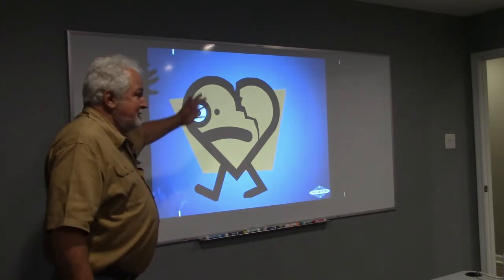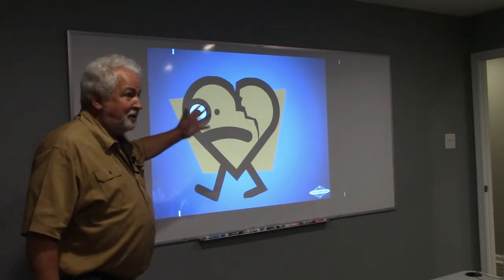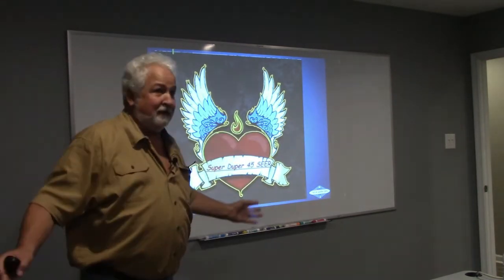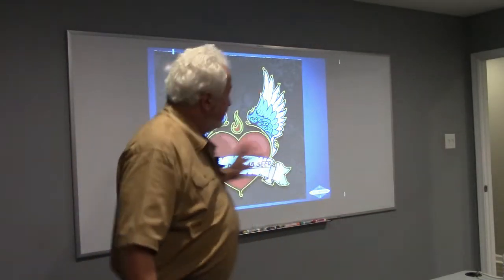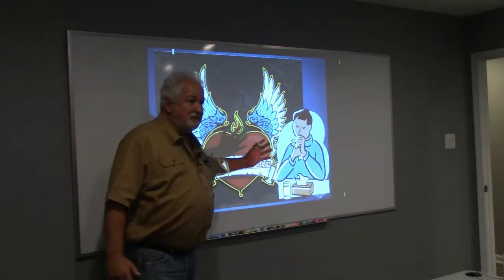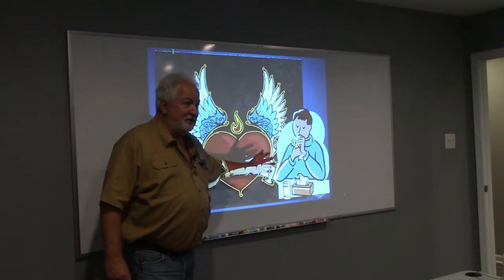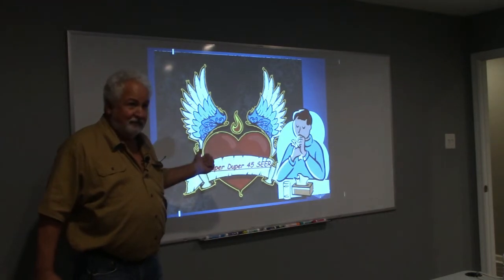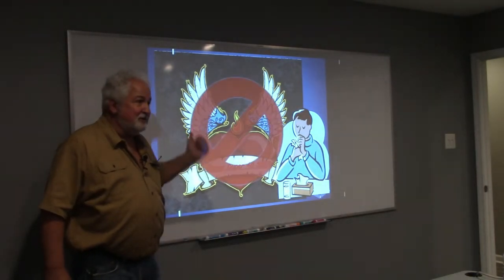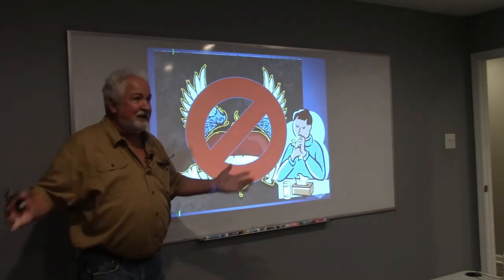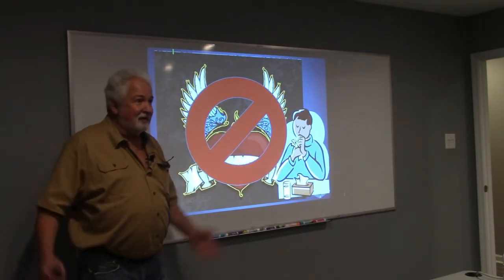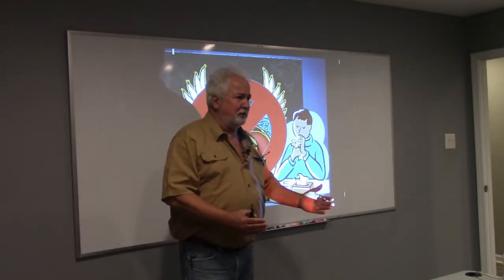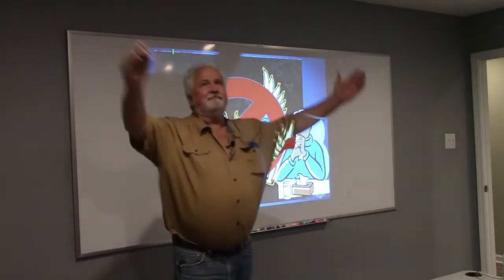So the compressor is broken, right? The compressor is broken, and you're going to put in the new super duper 45 SEER, whatever it is. If you apply that right on that asthma-ridden duct system, do you think you're going to get anywhere near the 45 SEER? No, you're not. Because you put it on an asthma-ridden duct system that can't breathe. Not compatible. Not going to work. So what do we have to do if I'm going to put in the 45 SEER? Upgrade the ductwork to that.